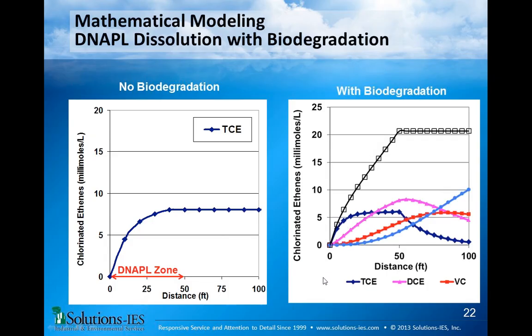Okay. I developed a little mathematical model here. It's certainly not the most sophisticated one, but I did this to illustrate what I think are some of the issues here. The way I represented it, first there's an initial step where TCE dissolves. So the change in aqueous TCE concentration equals a mass transfer coefficient times the surface area of the DNAPL droplets times the difference between the TCE solubility and the TCE concentration in water. That's the driving force, and that adds TCE to groundwater.